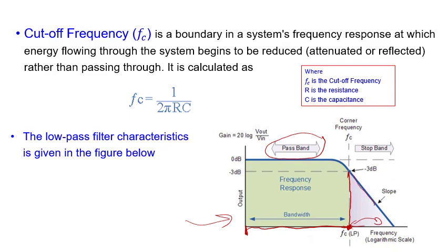Now, where do we select this cutoff frequency, at what point? It's at a certain point, not at the knee here. We are not selecting it here. We allow the voltage to drop to a certain level, which we call 3 dB. When we reach this point, any frequency after that is considered rejected. So again, I'm not going to take the voltage on the output to be maximum.